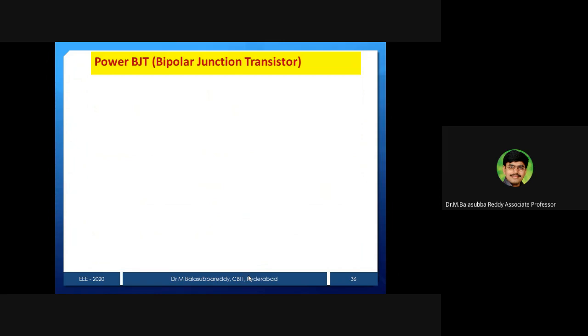There is a conduction resistance RD, which will be more. That's why whenever we are operating it, we get more power dissipation. That's why a MOSFET will be operated only in low rating applications. We cannot use it for high rating applications. But switching times are very small. That's why we can use it for high frequency operations, but not high rating operations, when compared to the BJT and all.